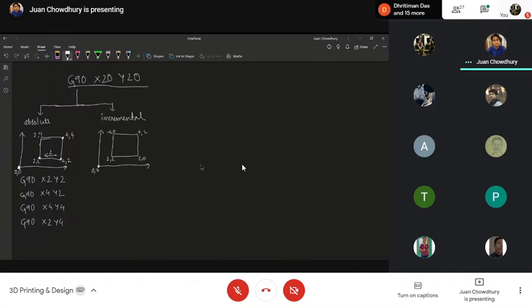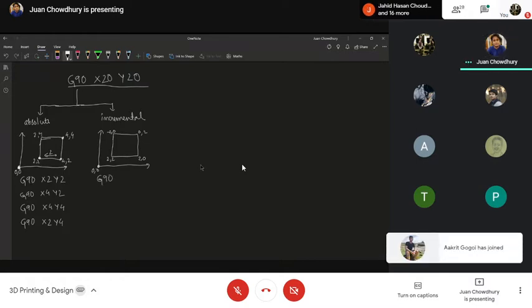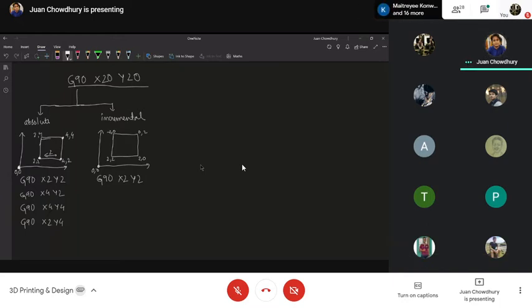So, sorry, it will not be G90, it will be G91 now. So G91 X2, Y0; G91 X0, Y2; G91 X minus 2, Y0. Is this concept clear?